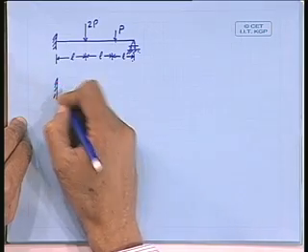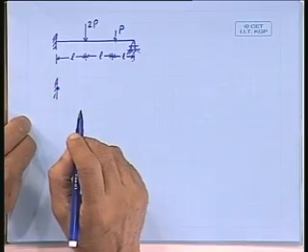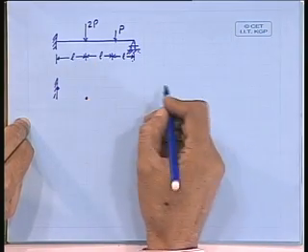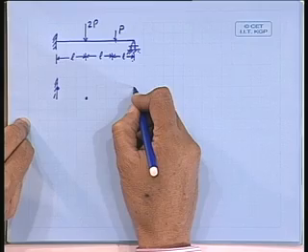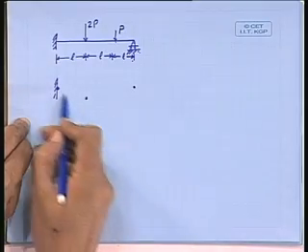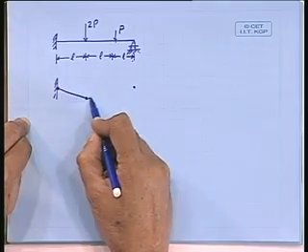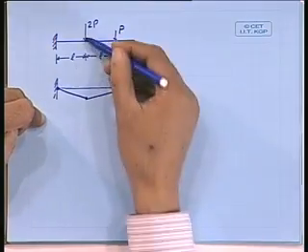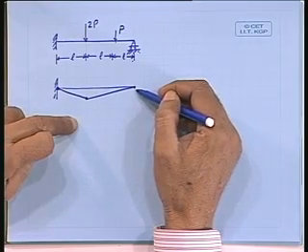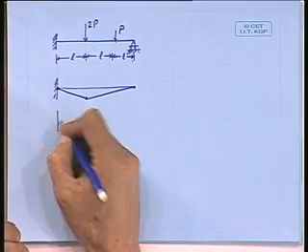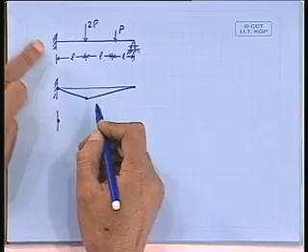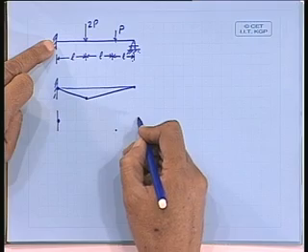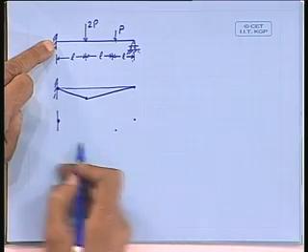Let me first assume that this support becomes a hinge, and this load also becomes a hinge. This is a support, so this is a hinge. So I can have one mechanism like this: one support, under load, and physical hinge. The second one I can consider that this is becoming a hinge, and the second load is becoming a hinge, and this support is there.